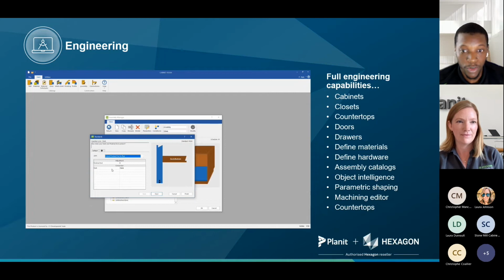The software will also allow you to control the dimensions you want to see, how you want to place the dimensions on the bottom, on the left, and what you want to capture with those dimensions from the floor, whether to include the countertop or not, and that will be saved in the style. And once you save the style, by simply clicking to create the section, the software will automatically generate this end view for you with all the notes around it.